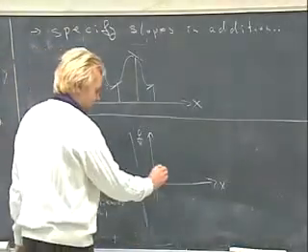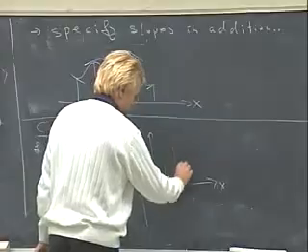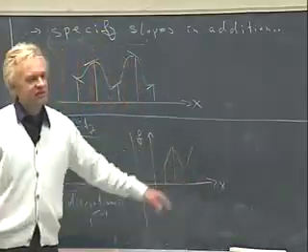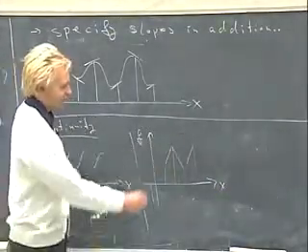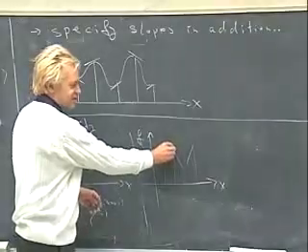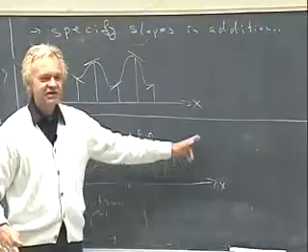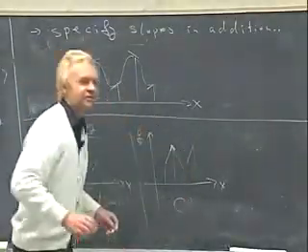This curve is continuous at the breakpoints, right? It doesn't have the same tangent here, right? There's a discontinuity in the slope, but at least the curve is continuous everywhere. So this is called C0 continuity.